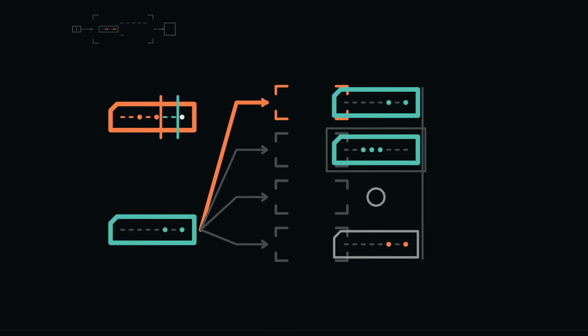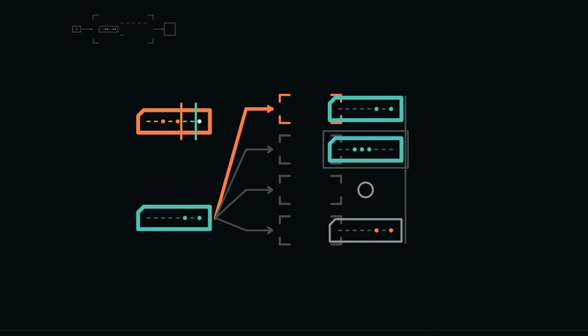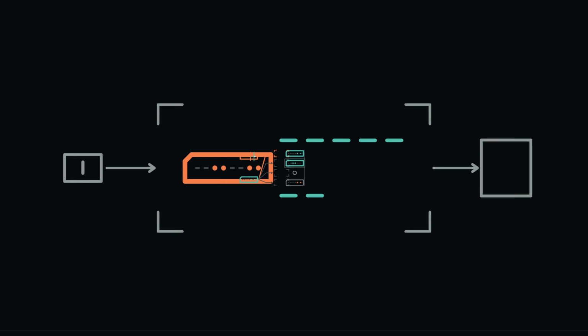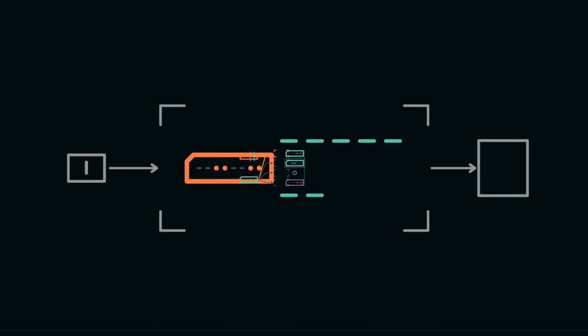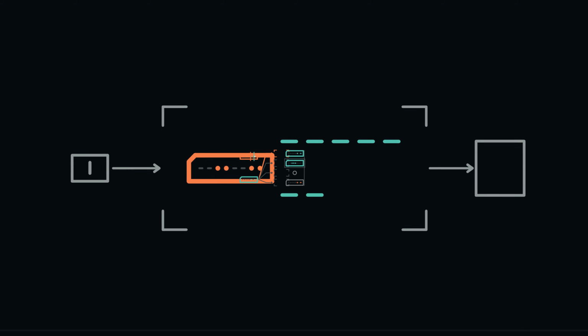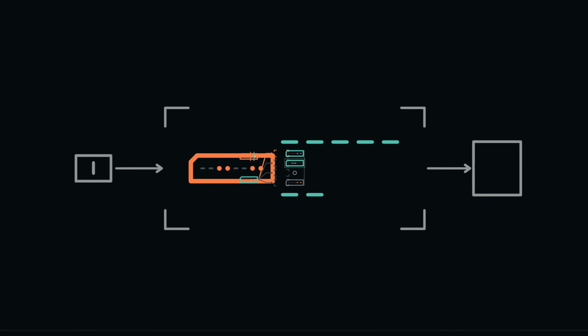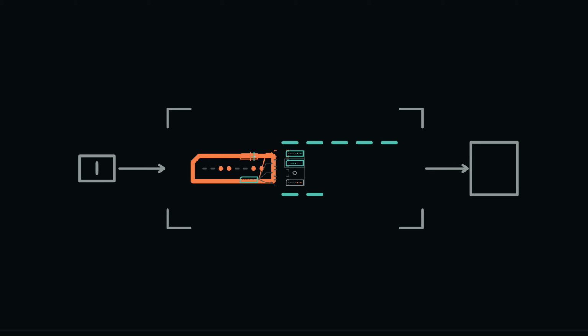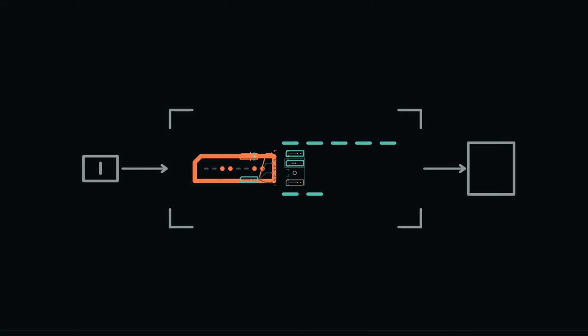Use the same decode procedure every time. Split byte 0 into opcode A and I. Let opcode name the instruction family. Check which fields that family permits and whether reserved bits are 0. Interpret B only in the role selected by that family and mode. Then state the exact allowed transition and flag behavior.